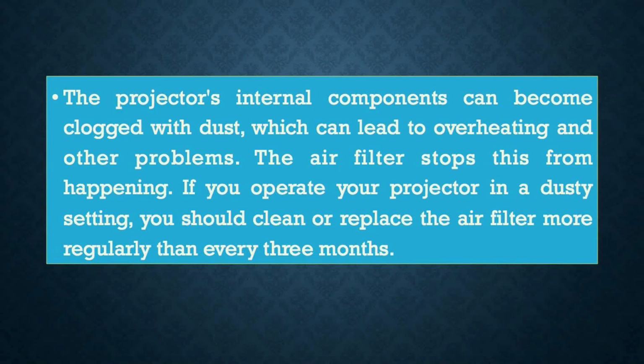Now the last point is cleaning of the air filter. A projector's internal components can become clogged with dust, which can lead to overheating and many other issues. The air filter stops this from happening. So if you operate your projector in a dusty setting, you should clean or replace the air filter more regularly than every 3 months.